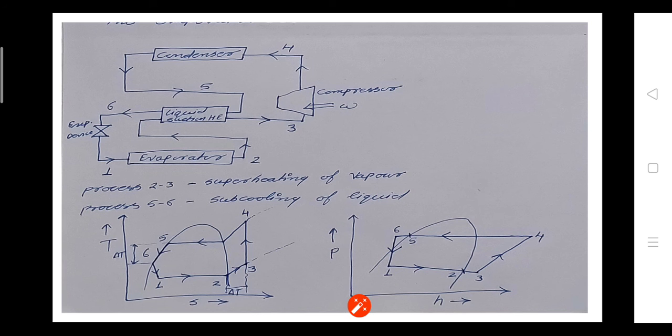Here in this heat exchanger, the hot liquid of the condenser exchanges heat with the cold vapor from the evaporator. Both the functions are here.